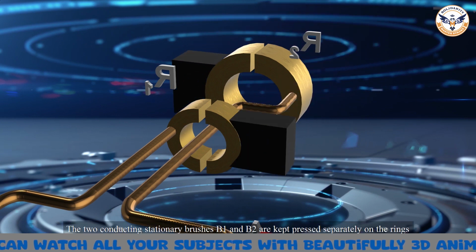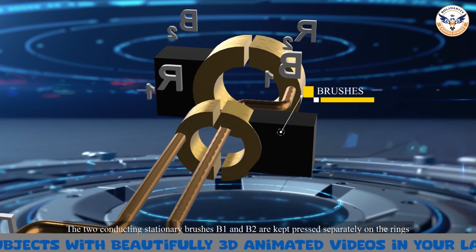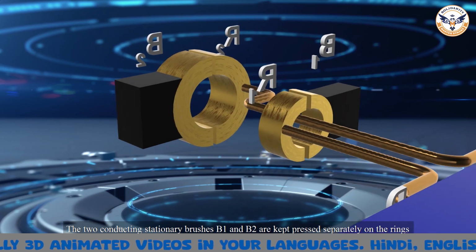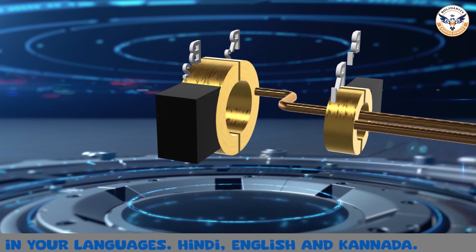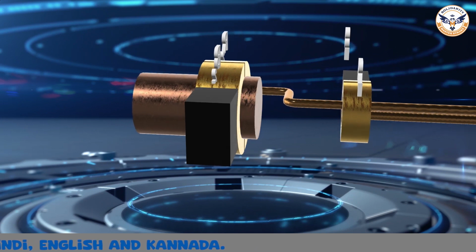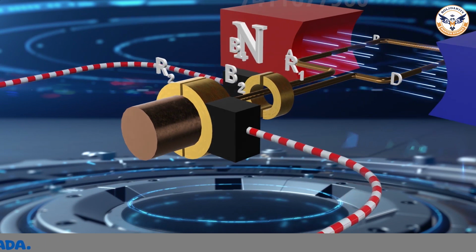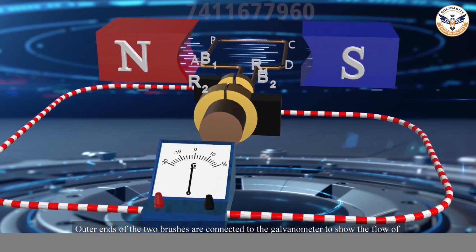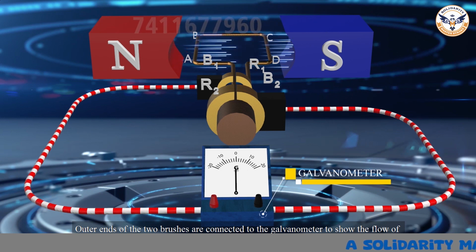The two conducting stationary brushes B1 and B2 are kept pressed separately on the rings R1 and R2 respectively. The two rings R1 and R2 are internally attached to an axle. The axle may be mechanically rotated from outside to rotate the coil inside the magnetic field. Outer ends of the two brushes are connected to the galvanometer to show the flow of current in the given external circuit.